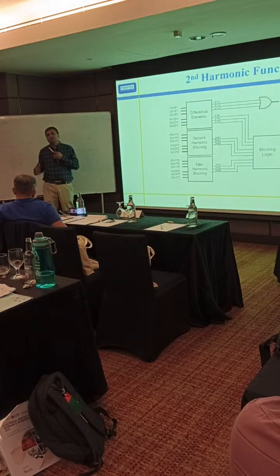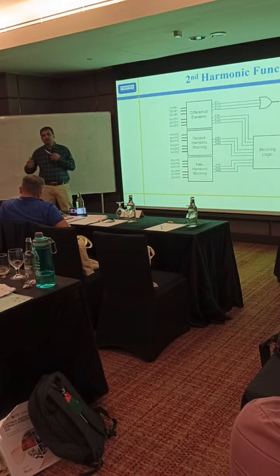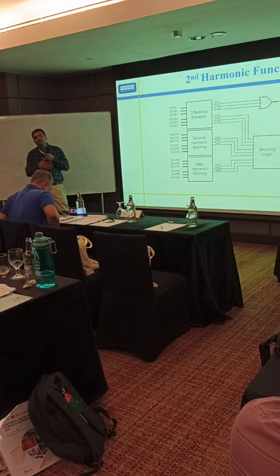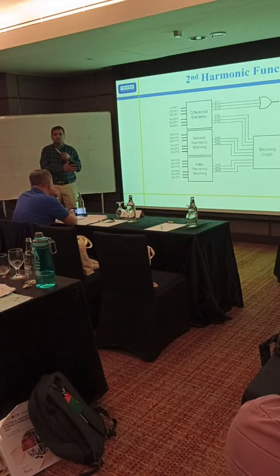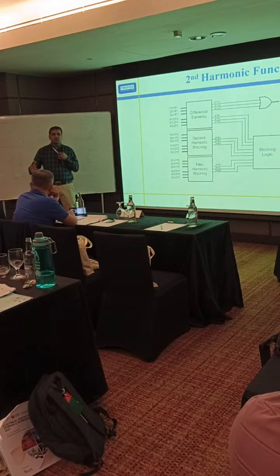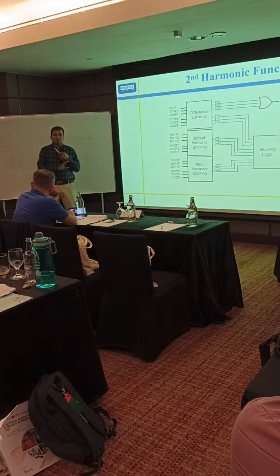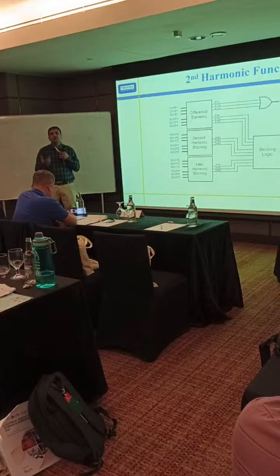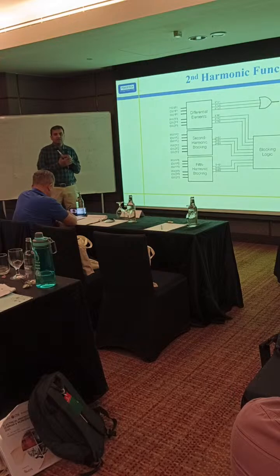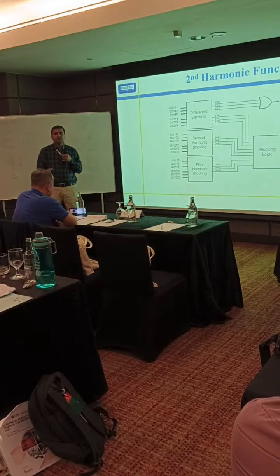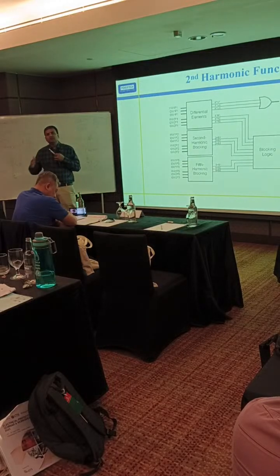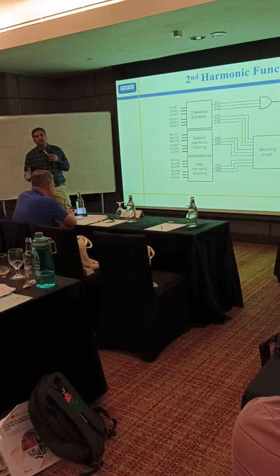Even if it is a nearby fault, in that case a through fault, we also want our transformer to be protected. At the terminal fault also, we do not restrict our transformer to be in service. Otherwise, due to so much high current, there may be mechanical damage. Although there is no internal fault, mechanical damage may take place. So in this case we want the transformer to trip immediately.